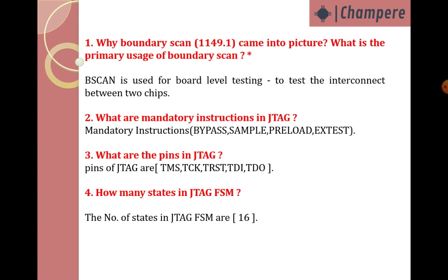And next question, what are the mandatory instructions in JTAG? The mandatory instructions in JTAG are bypass, sample, preload, and EXTEST. So these are the main mandatory instructions in JTAG. And what are the pins in JTAG?